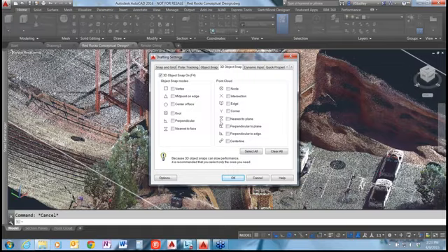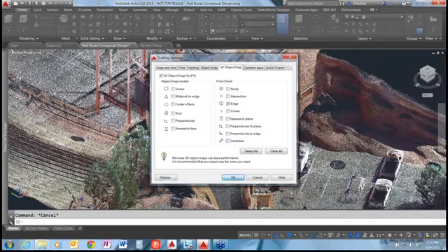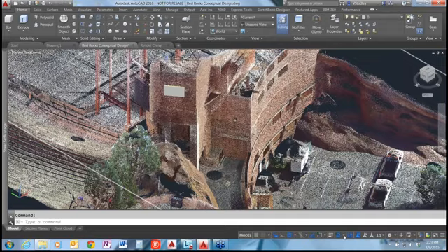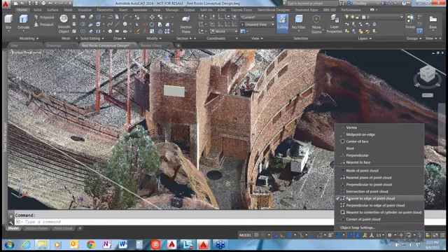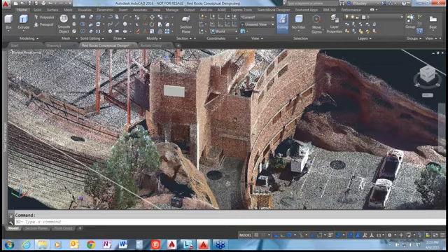Okay, so here's the point cloud section here. What I'm going to turn on first is, is it nearest to plane? Just make sure that I have the correct one. No, I'm looking for edge. Here we go. Let me make sure that's correct. Yep, there we go. In the drop-down menu, it's a little clearer: Nearest to edge of point cloud. And what this does is it's going to detect the intersection of two planes in the point cloud.